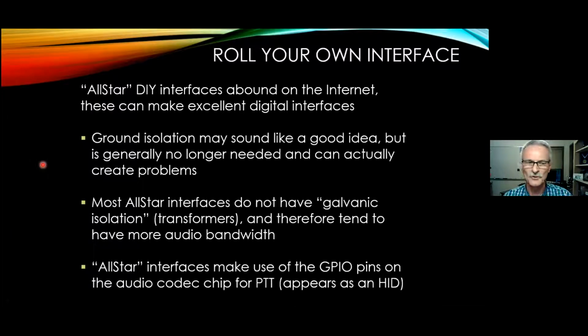Most of our computers these days operate off of a power pack that doesn't even have a ground connection on it. Or if it does have a ground connection, it's probably not tied to the negative side of the DC output from that going into your computer. I very rarely see any kind of ground loop condition going on these days. The other big problem with utilizing transformers is that they're going to limit the amount of bandwidth you have available, limit the amount of audio bandwidth.